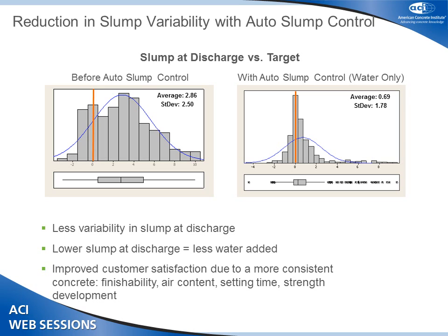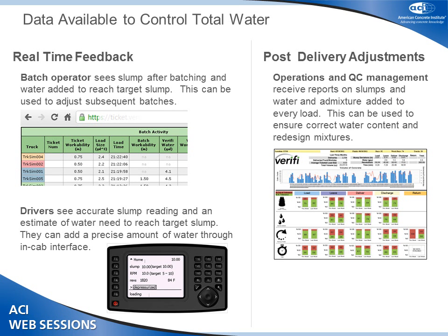And so this is not even putting in an admixture yet. So you get further benefit when you put in admixture. And also the fact that you're just measuring and displaying what the slump is helps reduce some of those controversies at the job site. So like I said before, the ready-mix producer has what he considers a 3-inch slump. The contractor has what he considers a 3-inch slump, and they're not necessarily what the cone measurement says is a 3-inch slump.